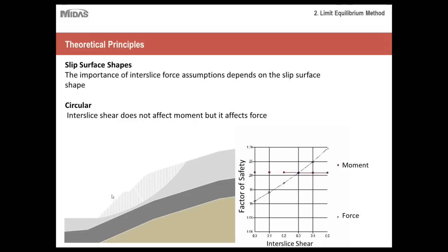Whereas if you were to take a horizontal force, so say you were to apply it sideways or laterally in this way, you would get some resistance, because of the way that the slip surface is oriented. That's why, as you can see, as interslice shear increases, the force on the factor of safety increases as well. So that's another important thing to keep in mind.